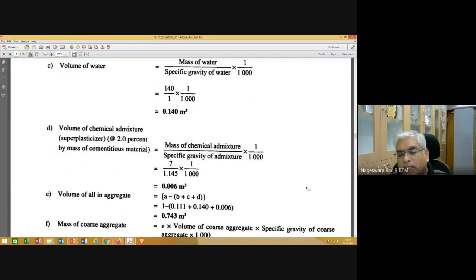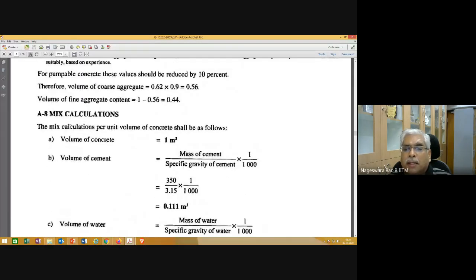And then once you do the testing, if the strength that you get is less than 40 MPa or much more than 40 MPa, then you need to make some corrections, come back to this trial mix procedure again, make the corrections, and then do one more trial. So this is an iterative process, or trial and error. We need to do 2 or 3 times to arrive at the correct proportions, either by volume or in terms of weight. You can see here, mix calculations.